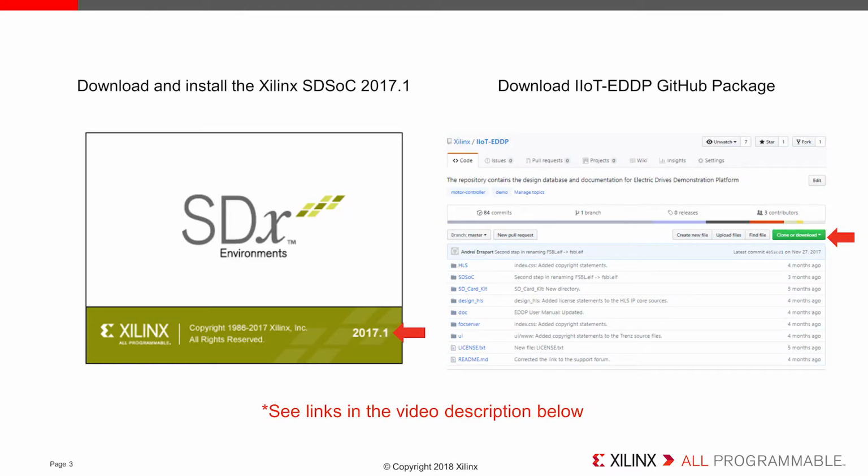The first step is to ensure that you have the required software and example design package for this module. This module is demonstrated using Windows, but if you are using the SDSoC GUI in Linux, you'll only see minor differences, so don't worry. You will need two items before you can start building the eDDP example design with SDSoC. First, you'll want to download and install Xilinx SDSoC version 2017.1 from the link shown here. SDSoC uses Vivado HLS behind the scenes to generate the hardware implementation, and you'll want to make sure that you use version 2017.1 for the best results from this module.